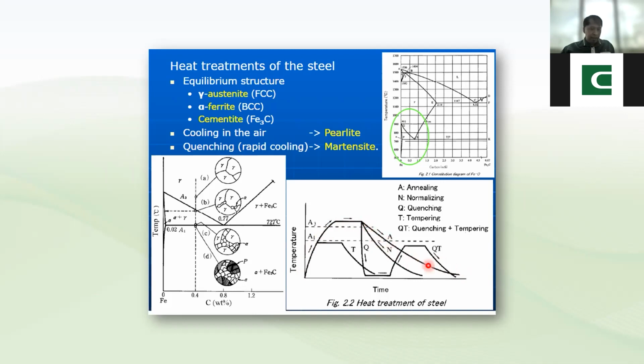So nagbabago lang sa pagpapalamig yung tatlong heat treatment process, no? Kapag sobrang bagal, ductile. Then yung second naman, pinalamig sa ordinary air, normalizing. Ano naman ang hindi sobrang bagal ang pagpapalamig? Pinalamig at normal room temperature, pinatay ang heater, ano nakikreate?